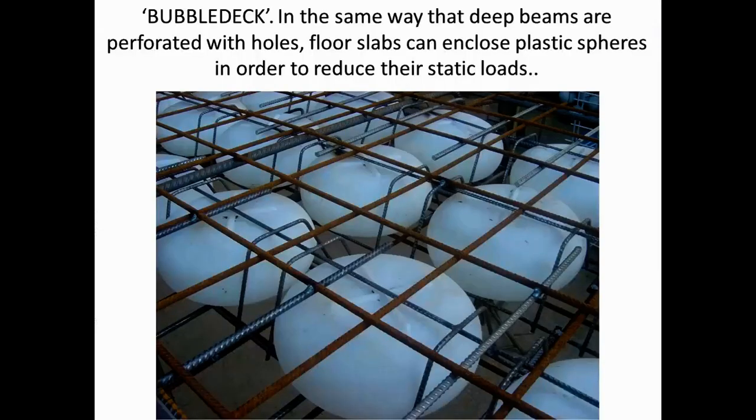Here's an interesting technology. We call it bubble deck only because I'm not sure that there is a generic term. The bubble deck is actually a trade name, I think. But as you can see from what's written there, this is the same principle, taking dead load out of the construction element. So remember earlier on we saw a beam that was castellated, then we saw a beam that was perforated. So this is a sort of three-dimensional version of that, isn't it? We've now got hollow plastic spheres inserted into the floor to take away mass where we don't need it, where it's not working for us.